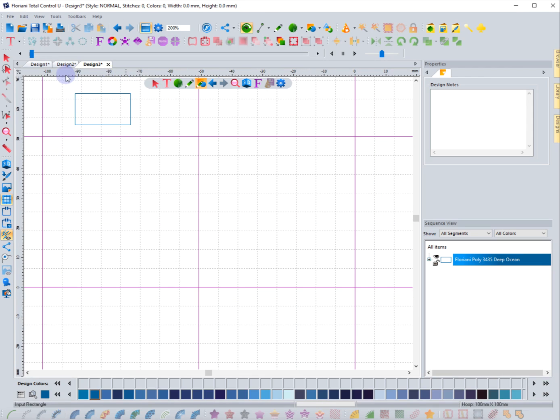If I come up to the ruler right here and I right mouse click and I turn on the snap to grid, now with a tool active, it's going to snap. You can see as I get close, it snaps down, and it will create kind of a perfect shape, like that's a perfect square, or rectangle is very even. It's a great way to utilize the tools and to be able to create things that are all the same size. So it's a very easy thing to do.